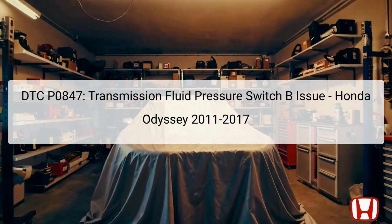The Diagnostic Trouble Code DTC P0847 indicates a problem with the transmission fluid pressure switch B related to the third clutch in your Honda Odyssey from 2011 to 2017. This code suggests a short circuit or that the switch is stuck in the on position. The transmission fluid pressure switch plays a vital role in monitoring the pressure of the transmission fluid, which is crucial for the proper engagement of gears.